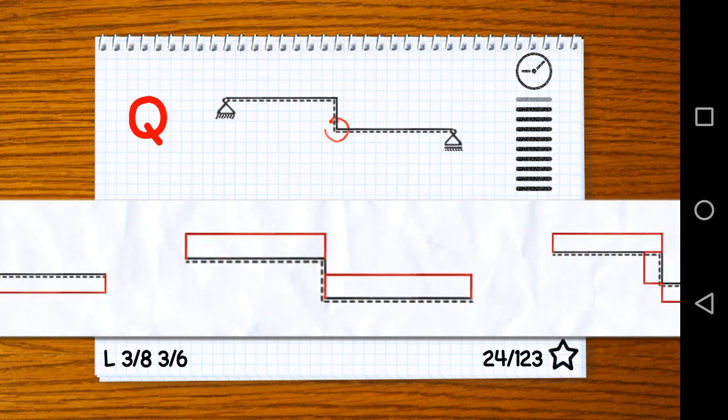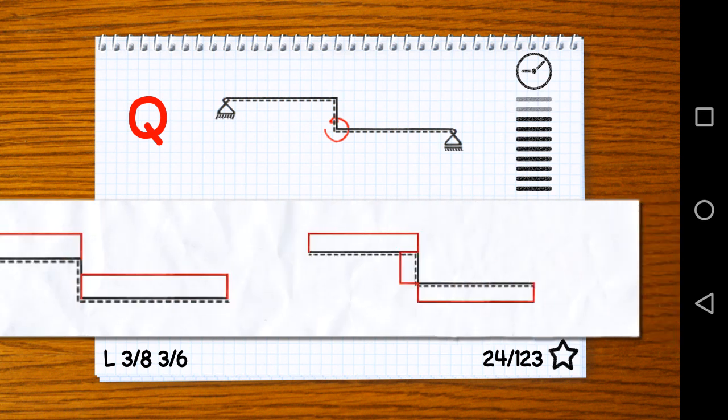Good. So the left answer here is wrong because we have no horizontal force in this system. So if we perform a cut on that vertical element, we should have no shear forces. Here they have shear forces in the vertical element.